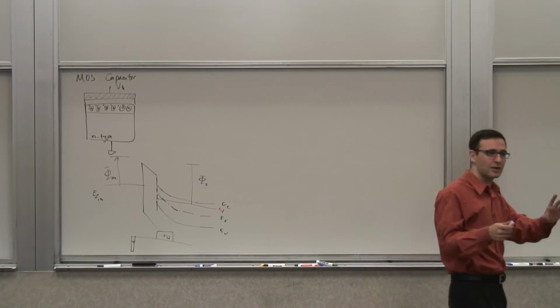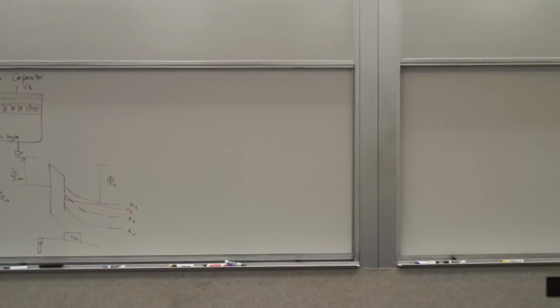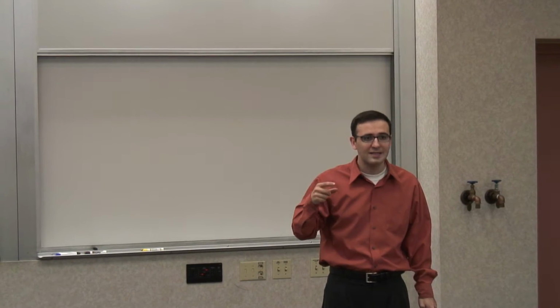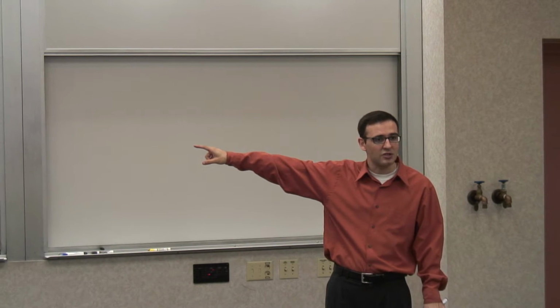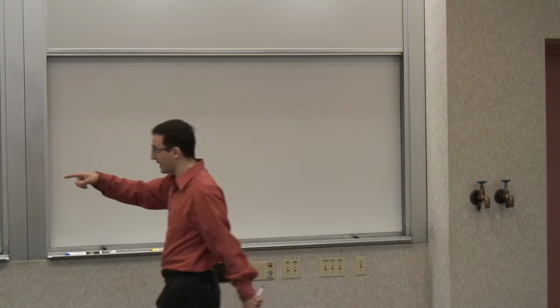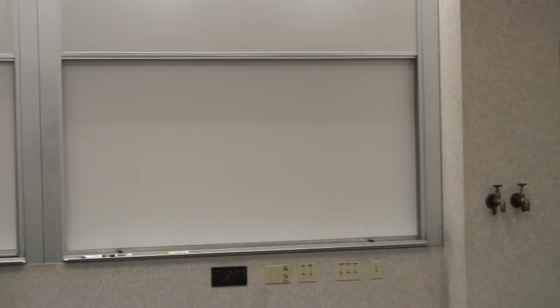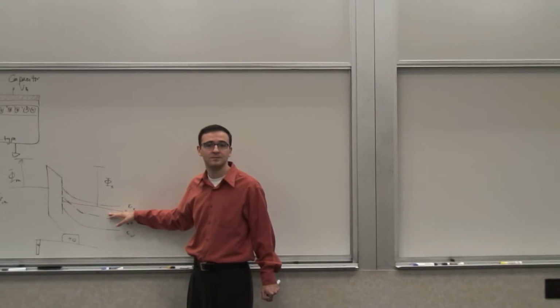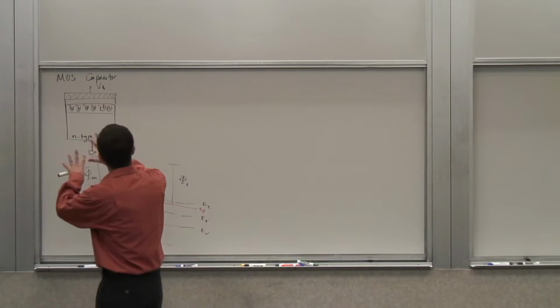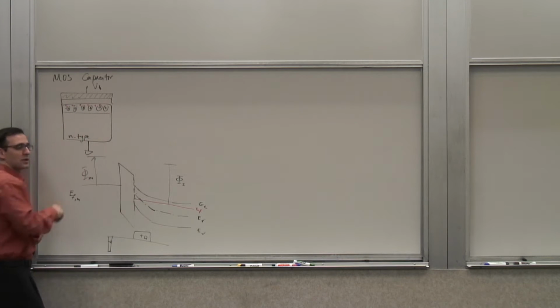So we saw that if you look at this capacitor and you apply a very large, very high frequency sinusoidal signal to it, instead of getting the inversion layer changing, you will see the depletion layer changing. And that's inconsistent with this picture, as it should be, because that's not thermal equilibrium. But if you wait long enough, this is what's going to happen.